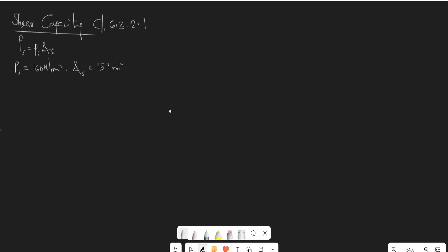There is actually a table for different grades. We have grade 10.9, we also have grade 8.8, we also have grade 4.6. So as it affects your application, please do stay with it. You can check your BS 5950, BS 4190, BS 4933 for this table for tensile area. Okay, so for this we are good. Now you can apply this to obtain your value.